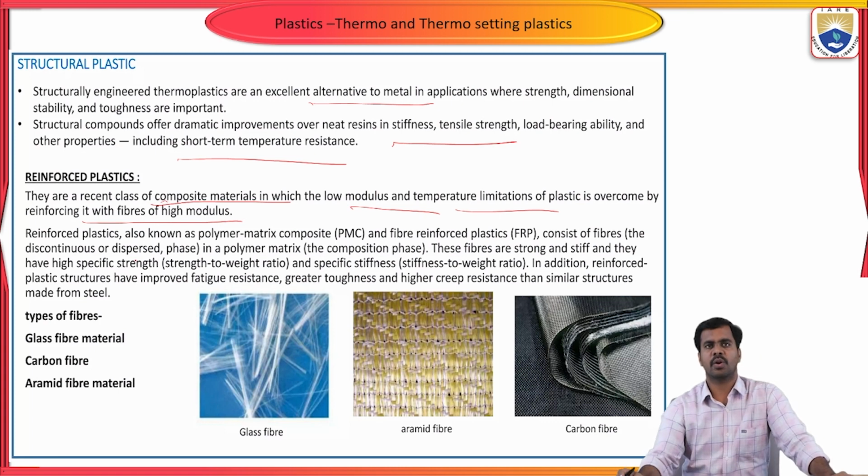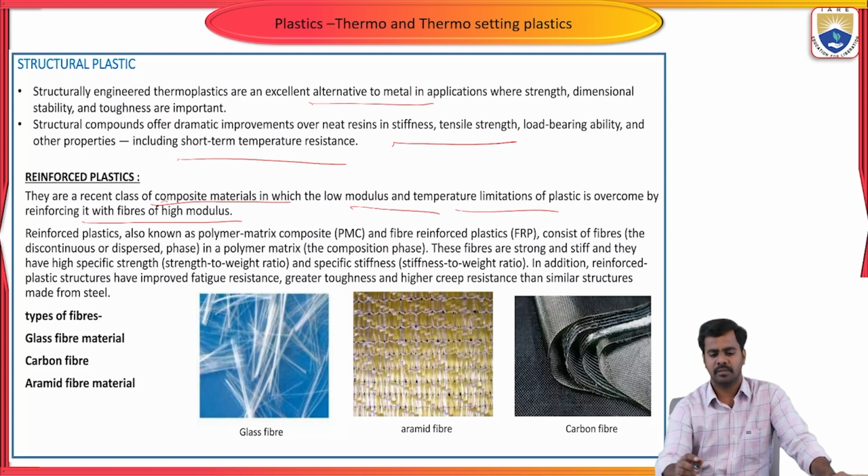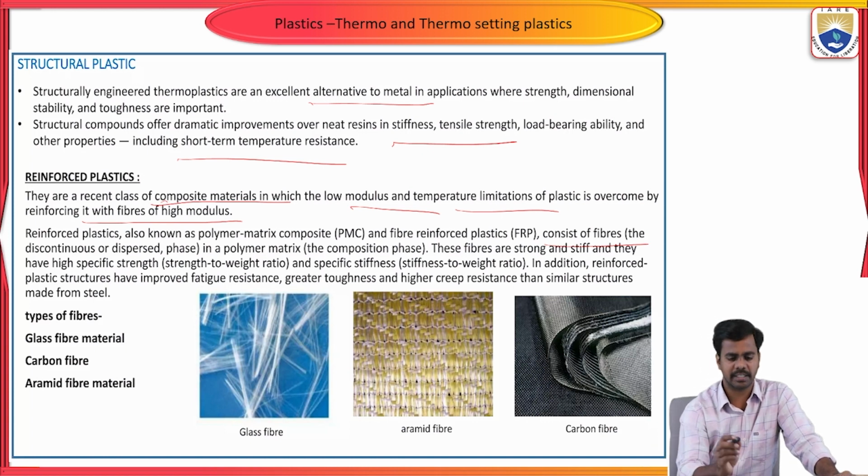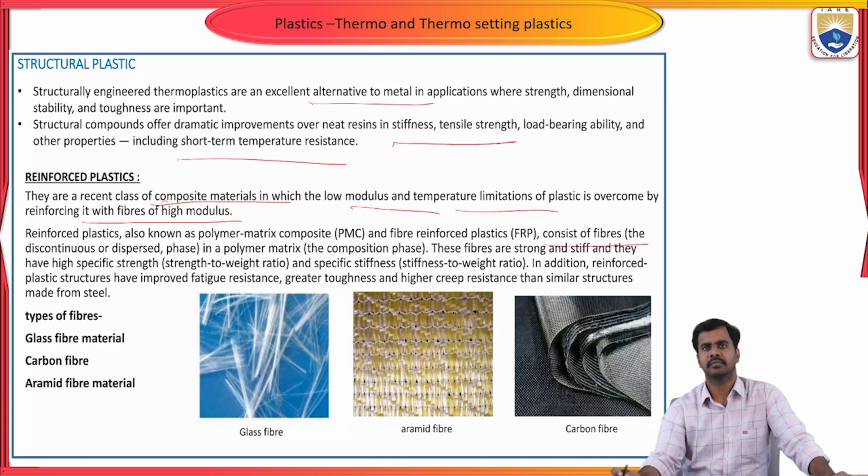Reinforced plastics are also known as polymeric composites and fiber reinforced plastics. So these consist of fibers, discontinuous and dispersed phase in a polymer matrix. These fibers are strong and stiff and they have high specific strength and specific stiffness.